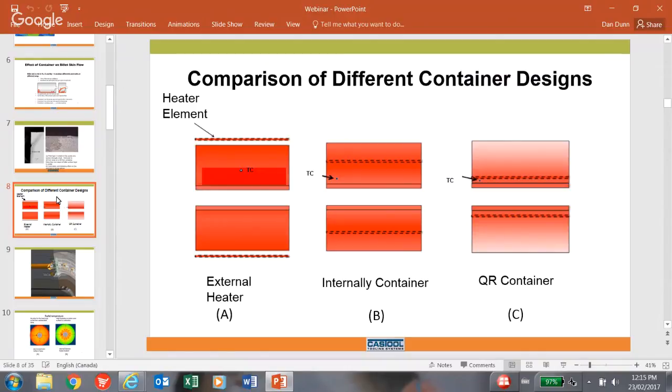In figure B, we see the thermocouple placement has moved, but still not in the optimal location. These elements have moved centrally to the mass as they focus to heat the entire container body. The element location still creates the same thermal constraints as in figure A design, with an increased opportunity for liner overshoot. In this design, we typically see multiple zones of air cooling on the liner.